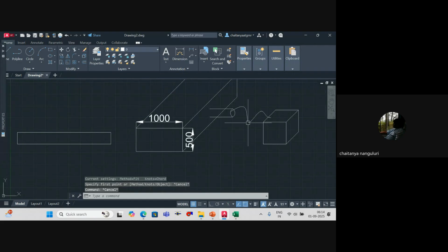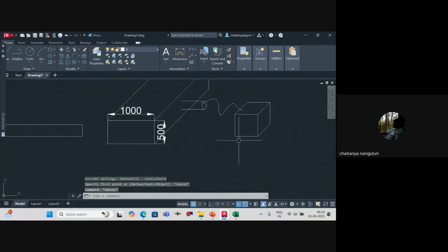On the side, you will provide a similar tapping like this. To that, you will connect. The bottom of this will be open, to which you will connect your diffuser or grill or anything. So air from this duct will enter through this flexible duct into this particular box. So if at the design stage this could be moved plus or minus, do you think this flexible duct is possible or not?